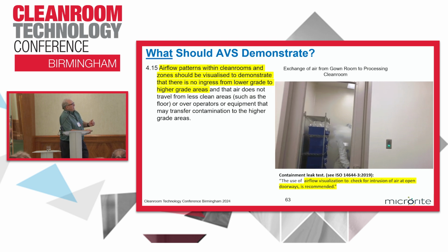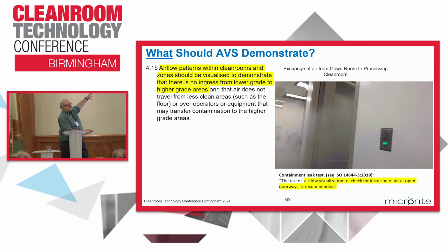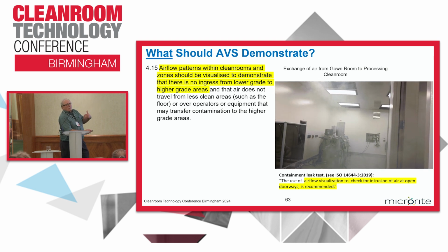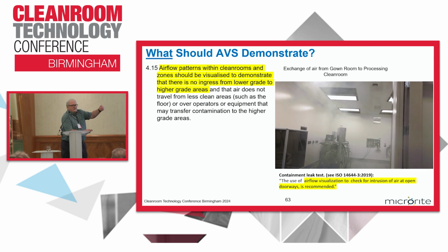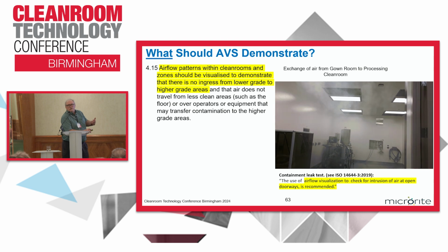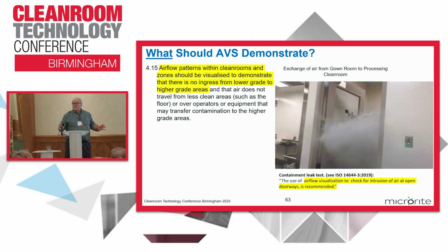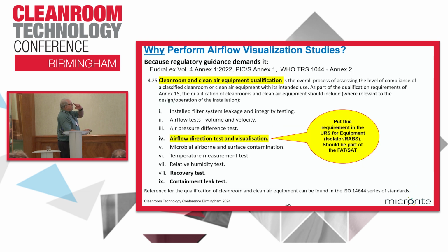One is the airflow inside the smaller room. We have 2 HEPA filters in there. We have 6 in the larger room. The placement of the air returns creates this piston effect. When the door opens, air from the gowning room rushes into the processing room. Right? That wasn't how the room was designed. They didn't understand that. They had the right pressure differentials, but didn't have suitable airflow in the implementation.